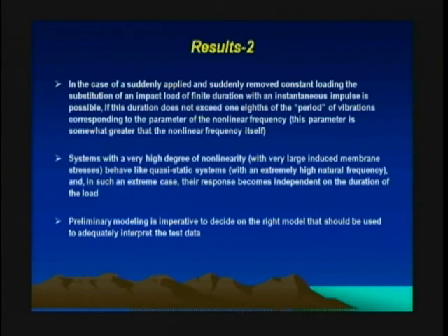Systems with a very high degree of nonlinearity, with very large induced membrane stresses, behave like quasi-static systems with an extremely high natural frequency. And in such an extreme case, their response becomes independent of the duration of the load. Now, after this result was obtained, we can understand its physics, but prior to that, it wasn't obvious. At the same time, we still have to answer the question of how nonlinear is really strongly nonlinear and how nonlinear is not strongly nonlinear. Preliminary modeling is imperative to decide on the right model that should be used to adequately interpret the test data.